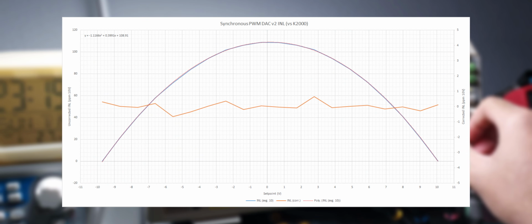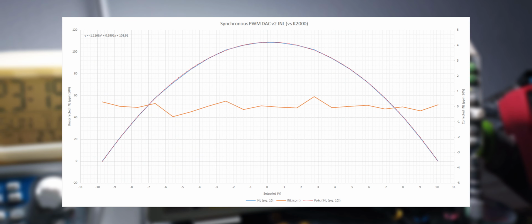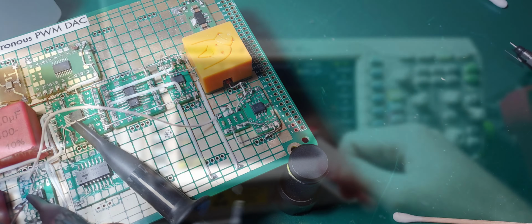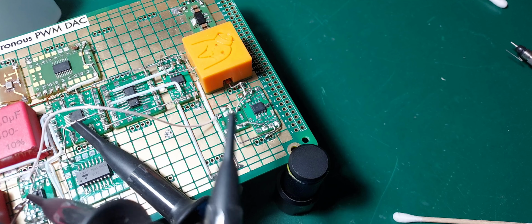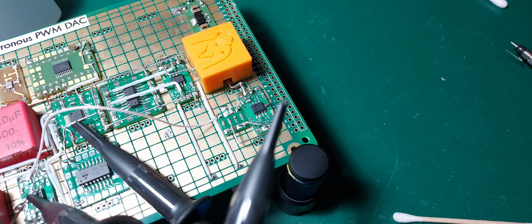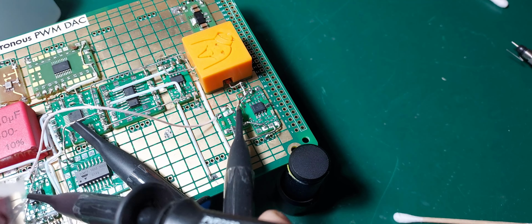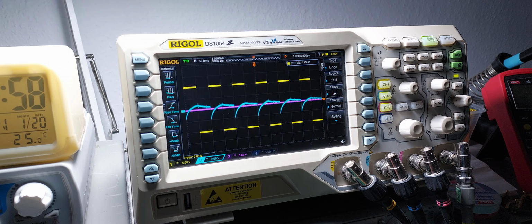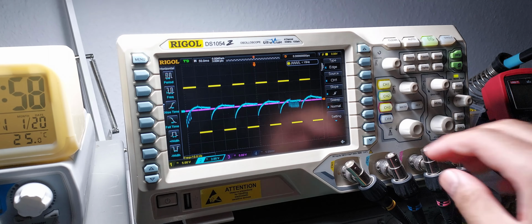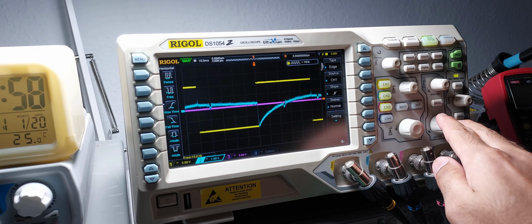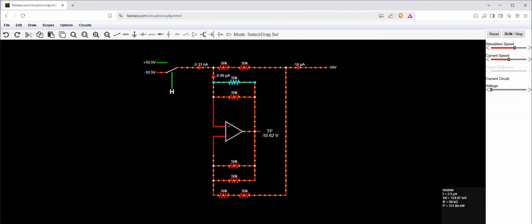Version 2 has the requisite linearity, but is somehow noisier than the previous revision, despite the larger capacitors. To characterize this noise better, I added a times 10,000 0.1 Hz to 1 kHz amplifier to the output. It looks to me like the bigger capacitors are loading the op-amps harder, causing the large downward spike at the start of each sample period. Another problem could have been avoided with better simulation.